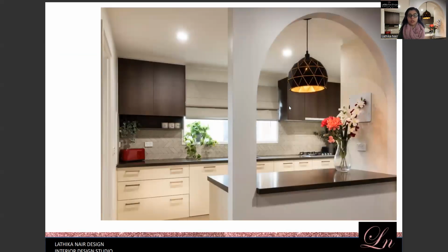Now in this example, you can clearly see the general light we have is the downlights. That is for the main passageway in between the island bench and the main cooking bench. Of course, we've got light under the cabinetry, but we don't have much. It's mainly the light with the range hood that lights up the whole cooking table. Other than that, because we don't have an overhead continuously, these two downlights are more than enough for the general lighting.